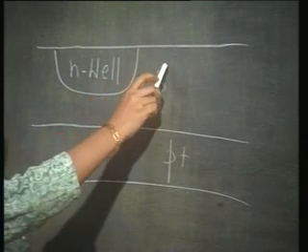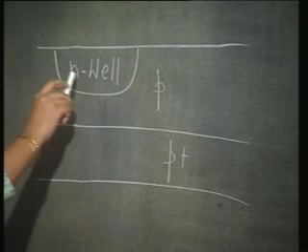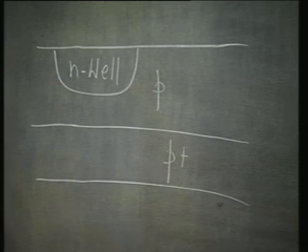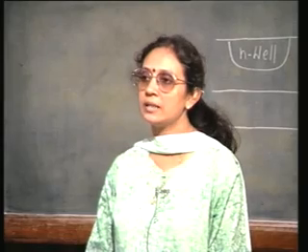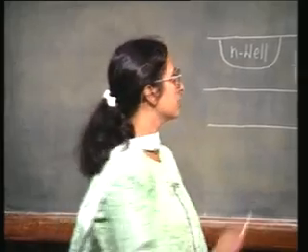This P type substrate can be used for the NMOS device, and inside this N-well my PMOS device will be housed.